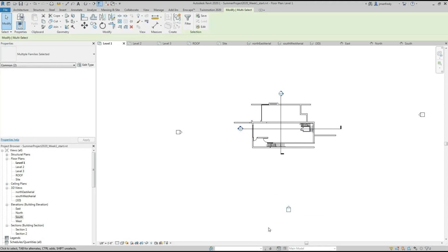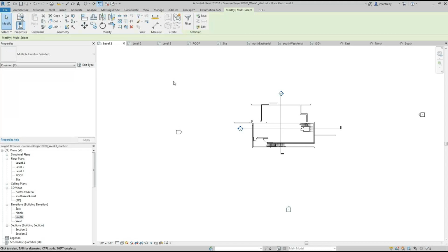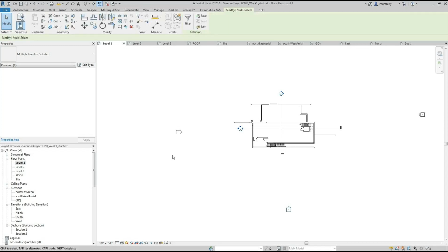If you erase the camera, you lost the south elevation, not the actual elevation in the 3D model. You lost the camera that's showing you the south elevation. And then you'll have to remake a new camera, remake a new view. And we all remember we talked about views are under the view command. I suggest you look here to recreate camera views of elevations. It's probably in there, but we'll do that later.